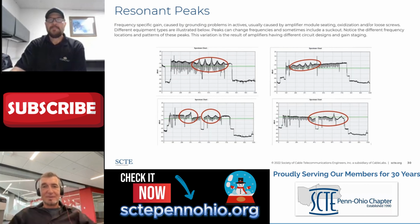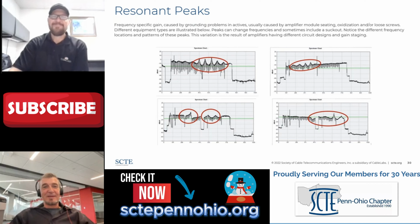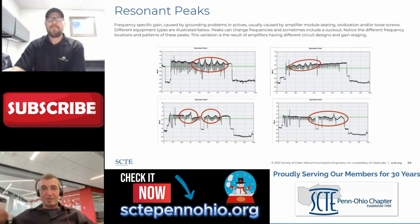I also do mechanics as a hobby, and everything I fix, I do a torque sequence on. And if you don't know it, just opposite corner, right? It's not that complicated. And anything is better than just going in a circle, tightening it as tight as you can go, and that results in incorrect torque being applied to the mechanical interface. So anyway, had to weigh in on that, Mike.